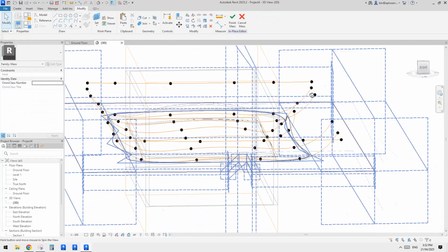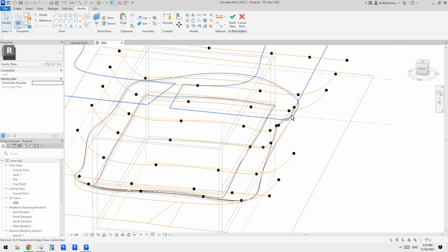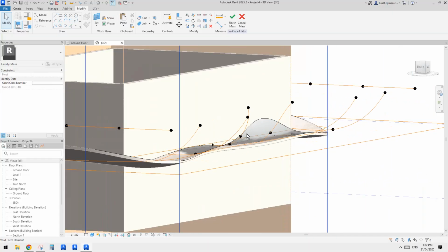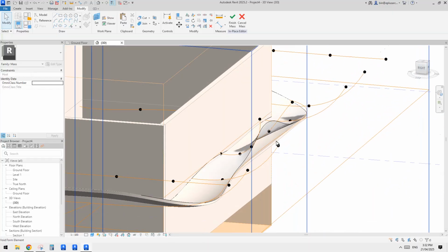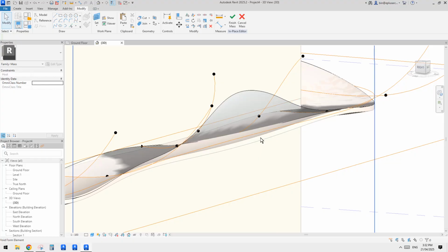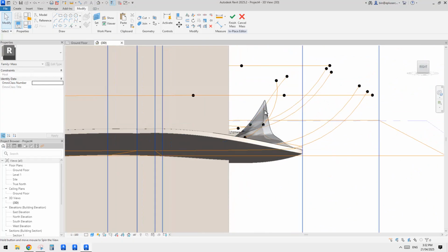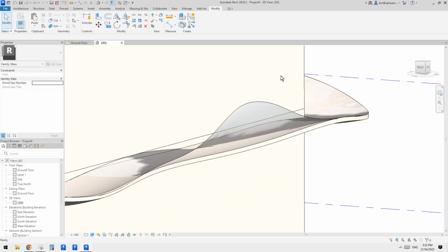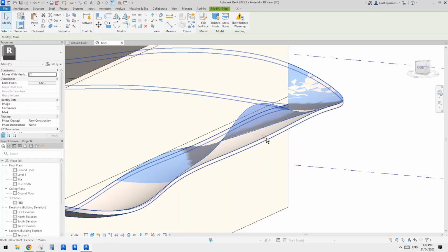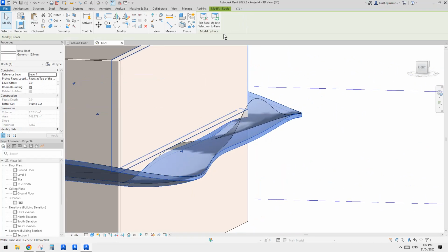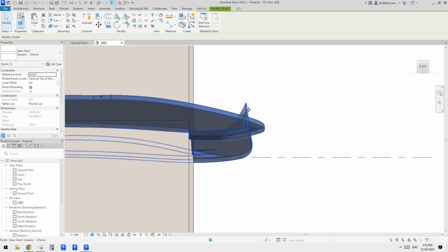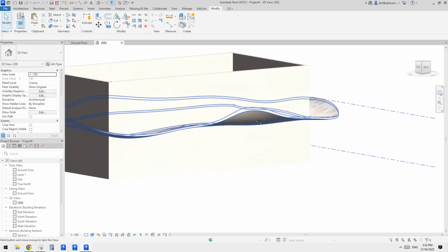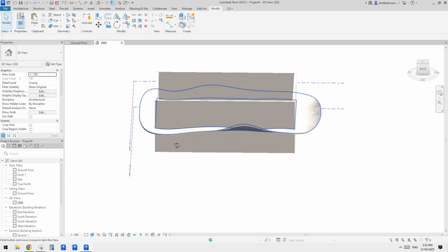So now let's type ASD shade. So now you can see this is that mass. So this is the previous floor. So you can see it's quite flat, but we curved this up a little bit. Okay, so now we can finish mass, select this roof, actually it's roof. So update, and it will match the mass. Okay, so this is how it can be done.